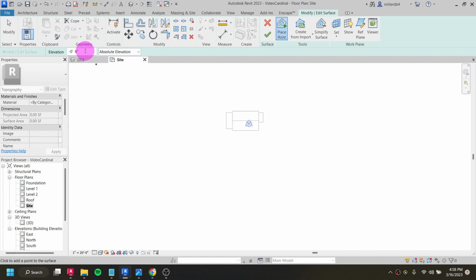So those are the various heights that we're going to put the topography within our house. So what I'm going to do is start off by just making an area that's sort of flattened out to be -6 inches. So I'm going to just highlight this elevation and I'll do -0 space 6. I don't have to type any units in because Revit is already going to think units of feet and inches. And I'll hit enter. And then I'm just going to start placing points.